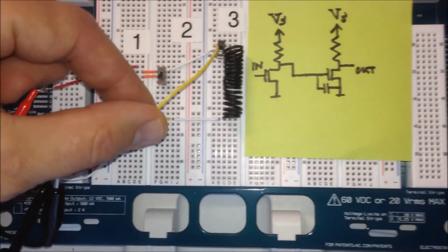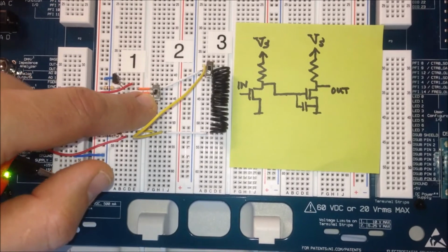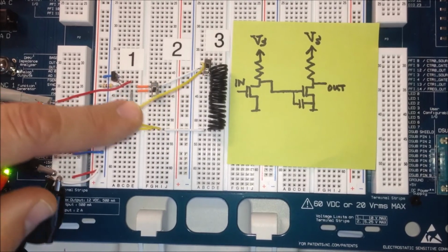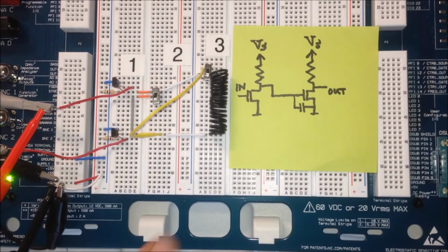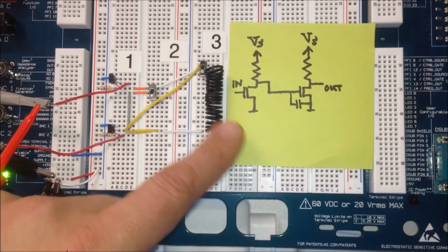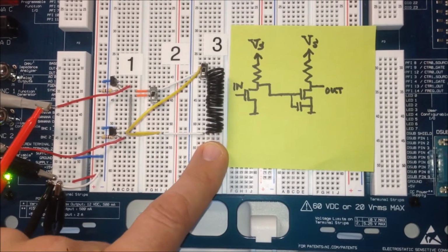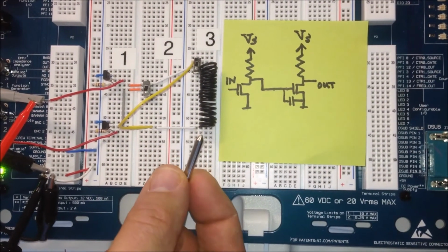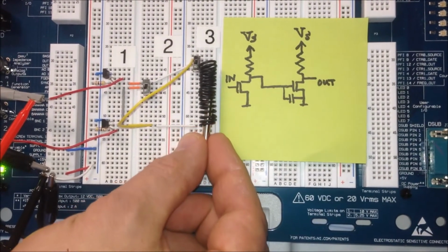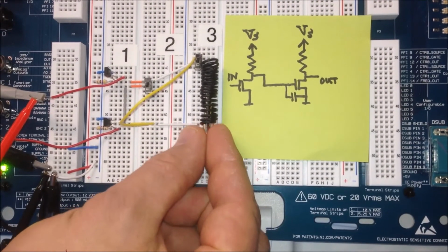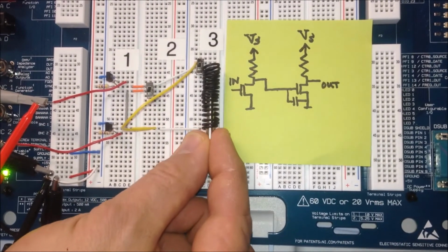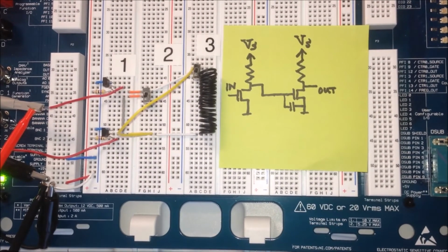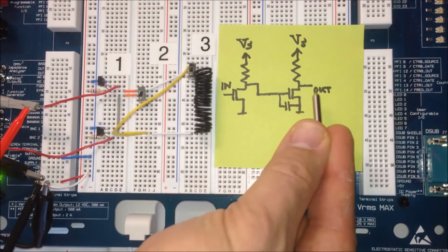So the second type of connection we're going to study is this yellow wire, and with this little switch we can replace the gray connection with this yellow, and it's exactly the same. The only difference is you can see it's longer. Then the final one we're going to study is this inductor. So this is a long coil of wire that we just made by hand, and we actually have here a little iron piece that we can stick into the inductor to change the magnetic field and the magnetization inside that inductor. So now let's see what those three different types of interconnects do to the output.